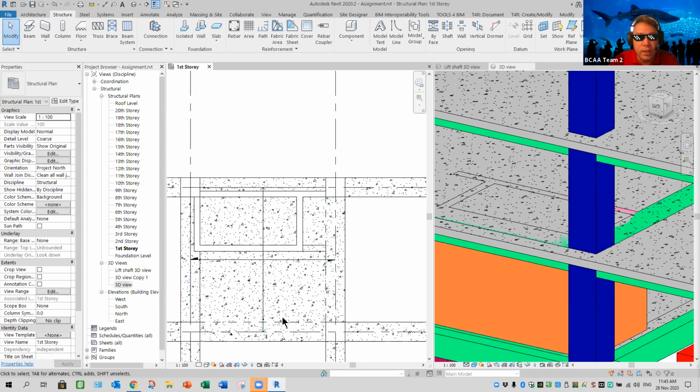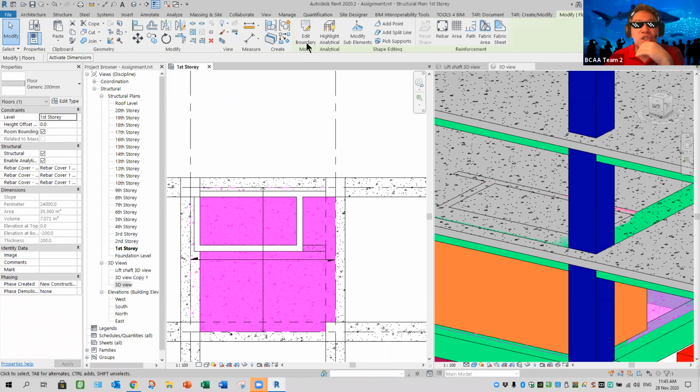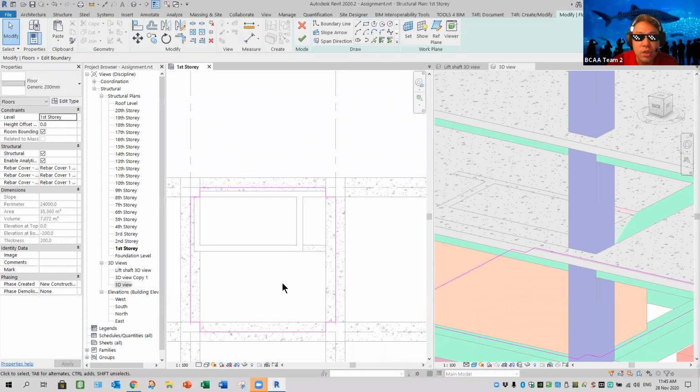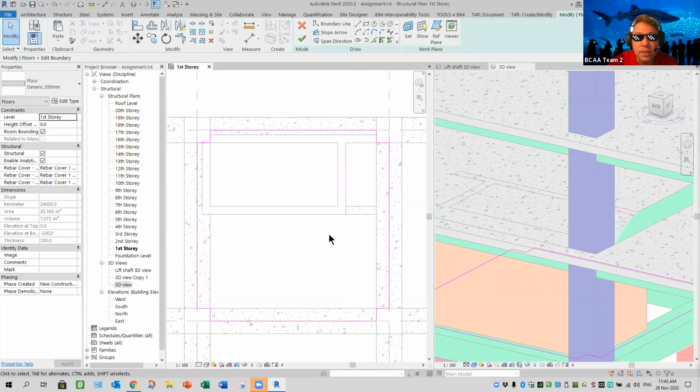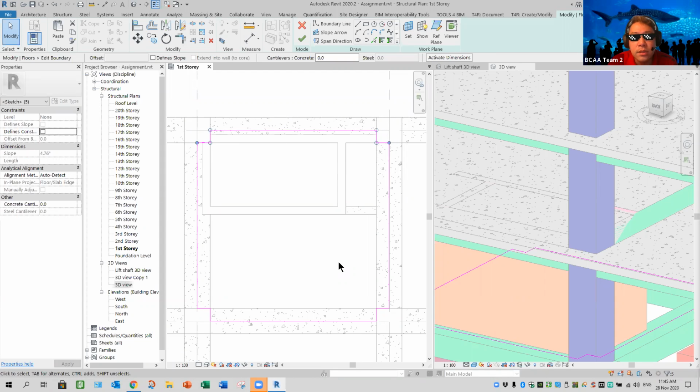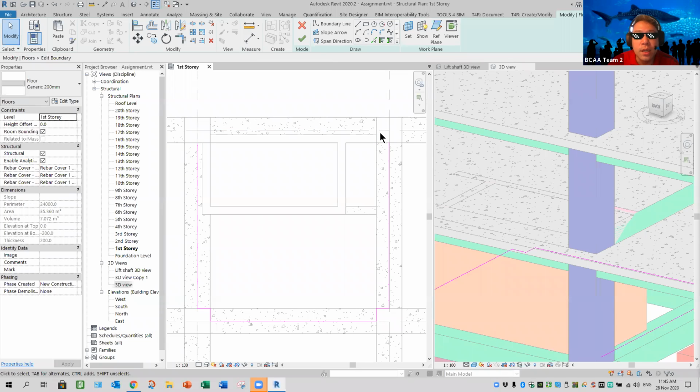In other words, if I set something like this, this slab means I'm going to adjust it at the boundary. It should not be constructed this way. It should be created as a separate slab. So for this particular one, this beam should be drawn like this. That means the line should be half of it here. So we can pick one here. Yes.